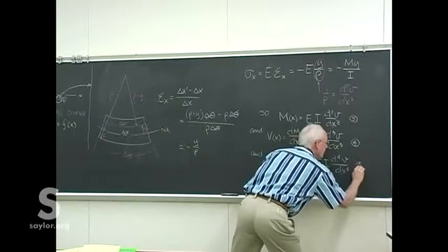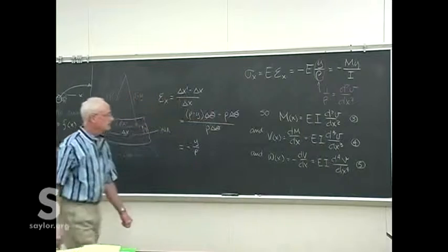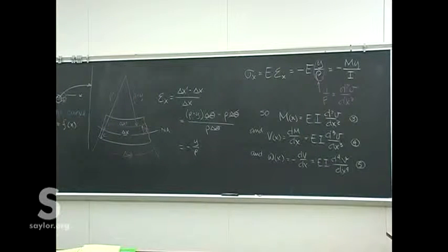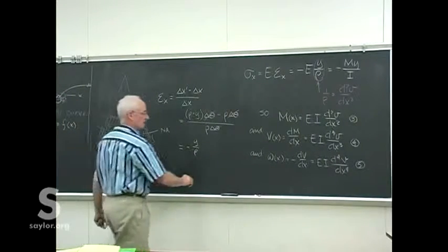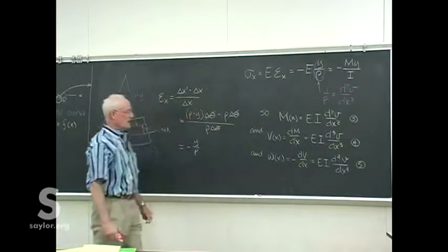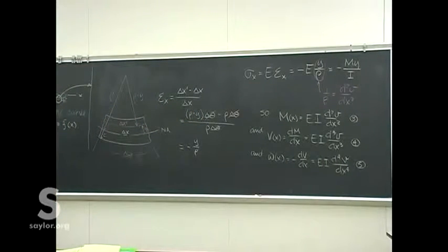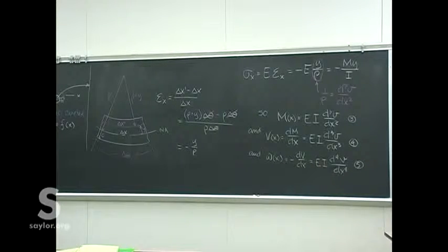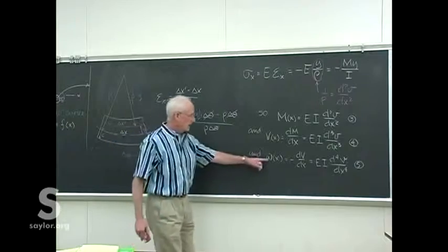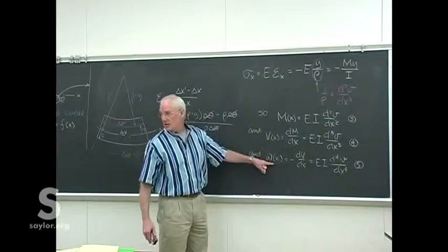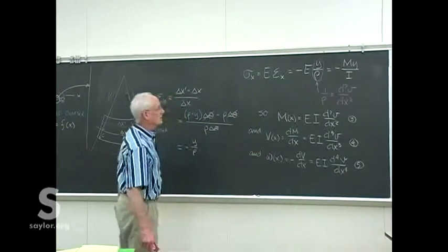And then we get our fifth equation now, as this fourth derivative of our load curve will be the load itself. Works particularly well if we have a distributed load. If we have a uniformly distributed load, then it might be easy to start right here and start integrating backwards.